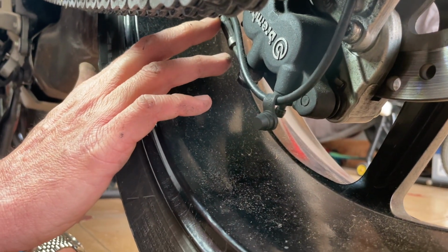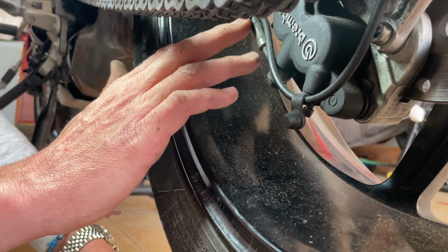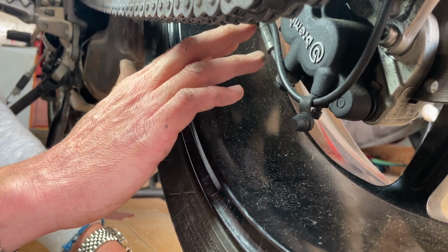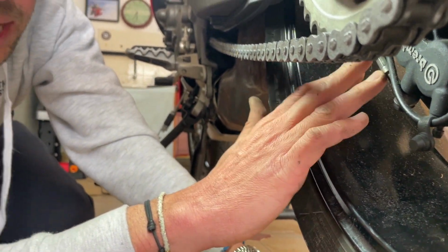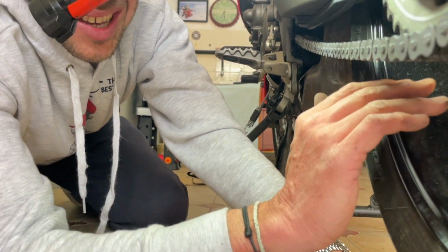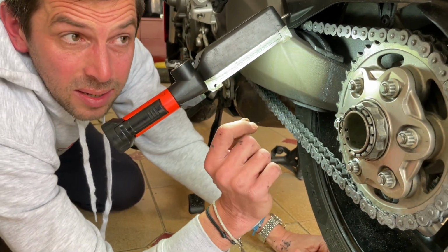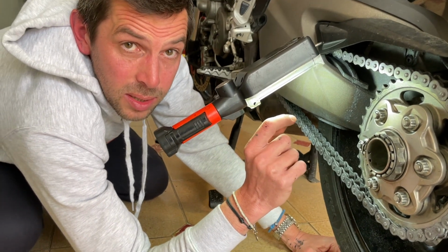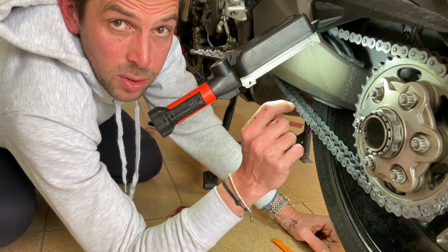Some bikes use software to facilitate the bleeding, but with the software or without the software simulation of the ABS module, you will in any case be able to bleed the system. In the most complex cases, eventually you have to disconnect a bit, untie a bit the brake hoses that go to the ABS module, but I do believe today we do not need to do that.